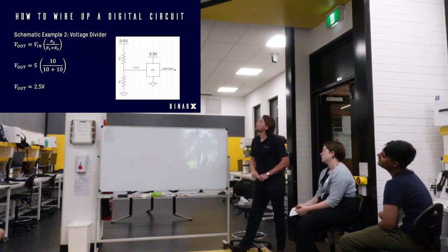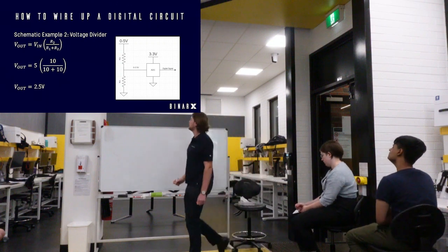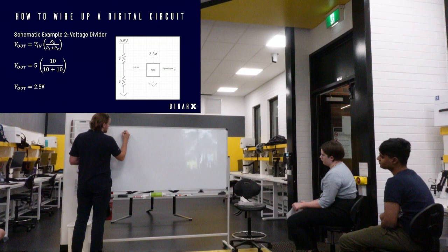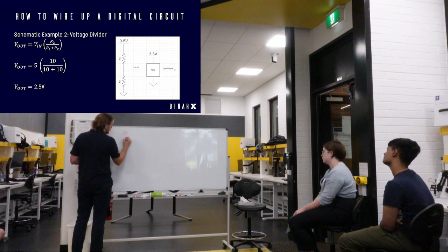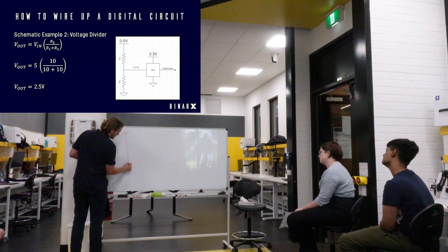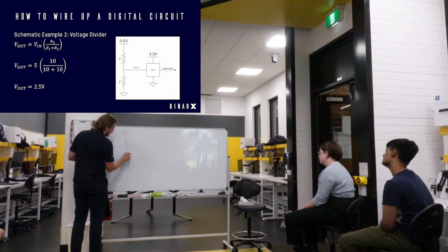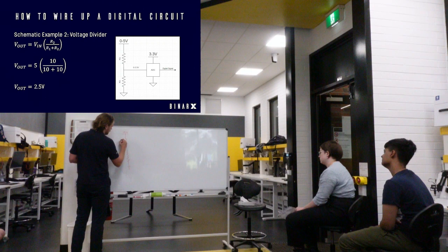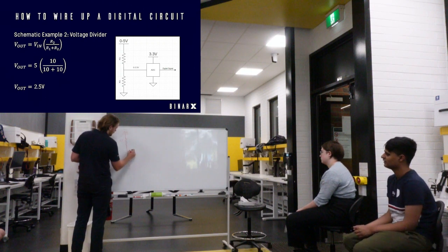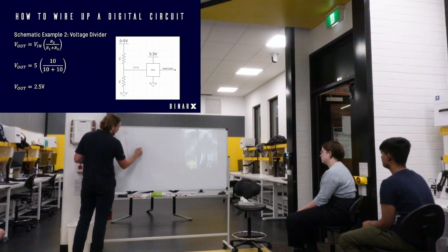So I'll do this again, but we'll assume that our maximum signal could be something like, let's say, 15 volts, coming in through our resistors like this. And I will say we need to know what this resistor is. We'll keep this one as 10K coming into our 3.3.